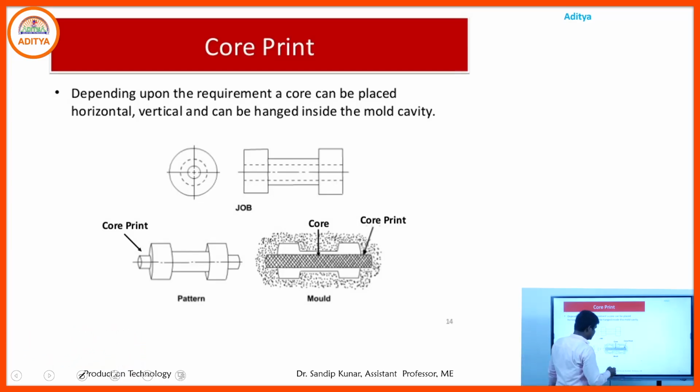If we look at that picture, that is the core print. If we consider that as the core, then the core prints help for positioning, locating and supporting the core in that particular mold cavity. That is the main function of the core print.